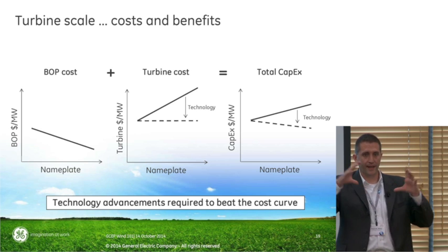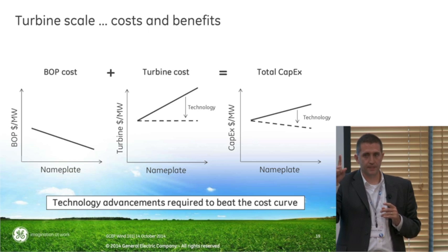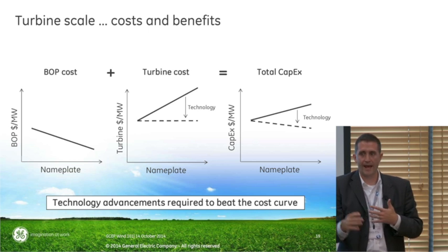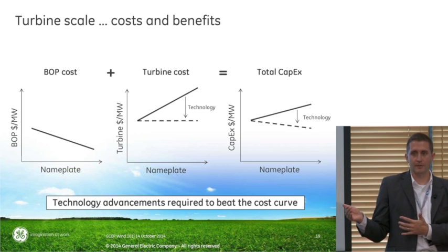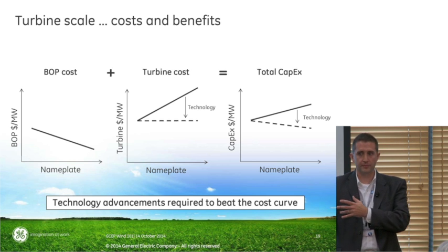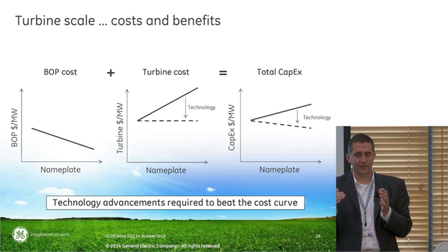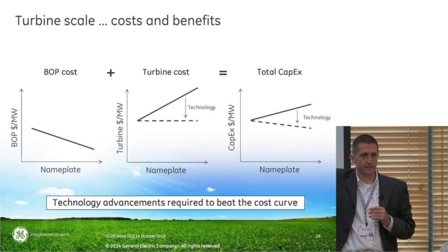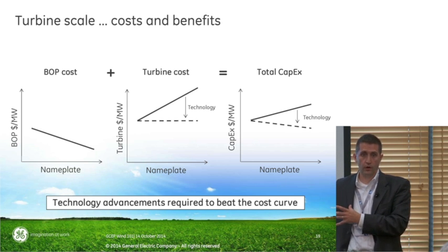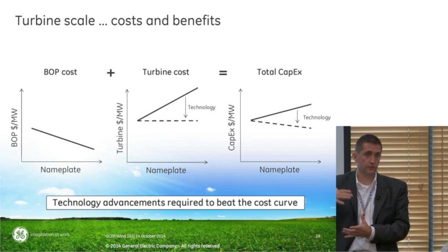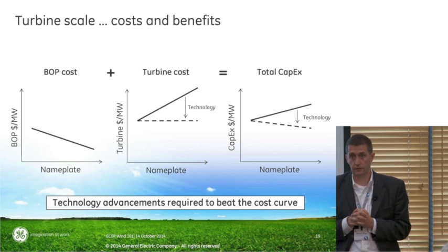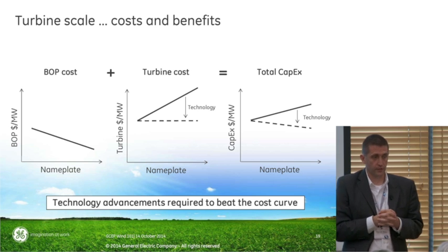So typically as you scale up, I'm not going to let my tip speed increase that much unless I can add some new noise abatement strategy on my blades, right? You can think noise is going to be a function, very simply, of the tip speed of my blade. So if I scale up bigger, I'm going to keep my tip speed the same, which means I'm going to rotate slower, which means I now have more torque going through my drivetrain, which is going to increase cost quite a bit. So there are those trades as you go up as well.